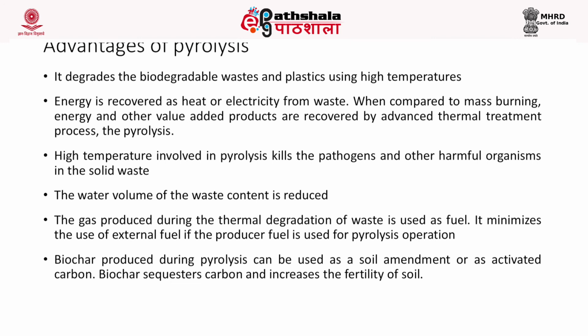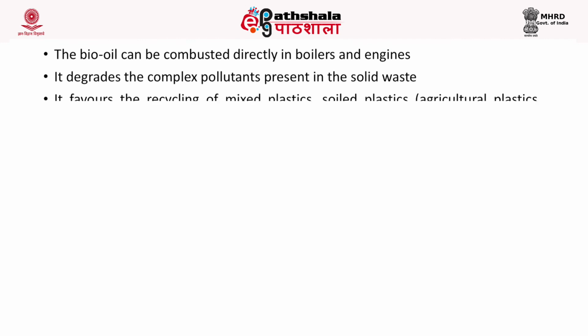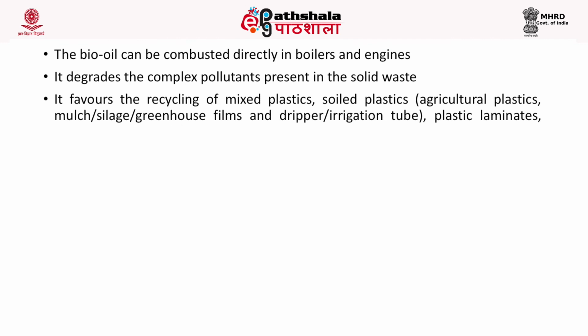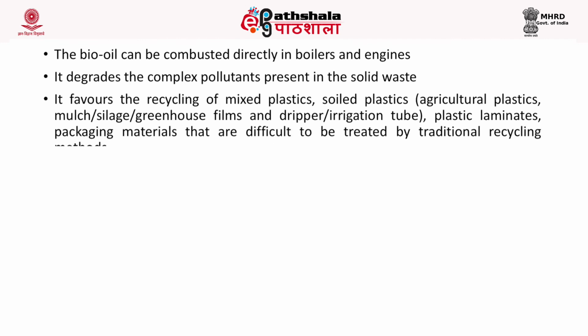Now, the gas produced during the thermal degradation can be used as a fuel, and it will minimize the use of external fuel if a producer gas is used for pyrolysis operation. The char that is produced during pyrolysis can be used as a soil amendment or as an activated carbon. There are also reports which say the biochar can sequester carbon and might increase the fertility of the soil. The oil produced can be combusted directly in boilers and engines.